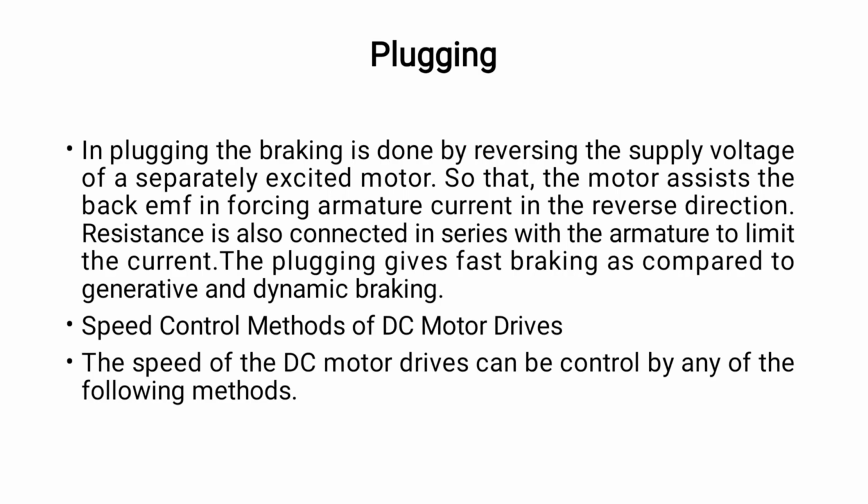Plugging. In plugging, the braking is done by reversing the supply voltage of a separately excited motor so that the supply voltage assists the back EMF in forcing an armature current in the reverse direction. Resistance is also connected in series with the armature to limit the current. Plugging gives a fast braking as compared to regenerative and dynamic braking.